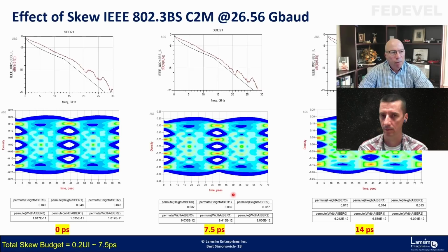If you don't have symmetrical return vias between the P and N, you'll get a bit of skew. Your breakout from your BGAs and so on, if it's not symmetrical, anything that causes asymmetry in your physical differential pair will cause skew to some extent on your board. And that will cause insertion loss. Exactly. More skew, and the insertion loss gets a little lower.